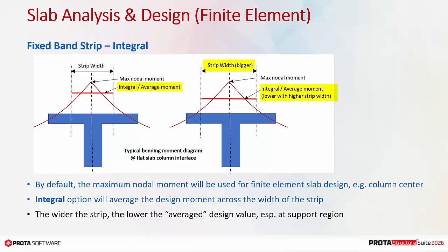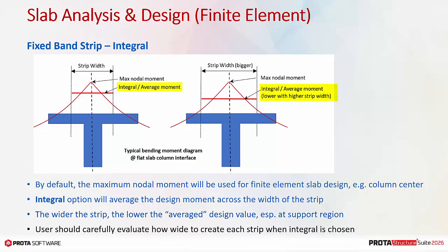As such, the wider the strip, the lower the average design value, especially at the column support region, where the moment changes abruptly. Hence the user should carefully evaluate how wide to create each strip when integral is checked, otherwise, the design may be too unconservative.